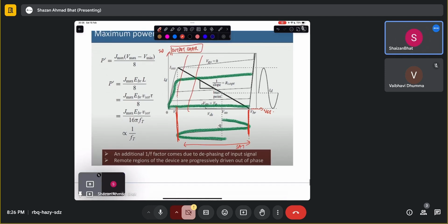This region. You want it all together to be in this particular region, so that it is in the saturation region and it should act like the amplifier you want it to act. And also the current swing should not go beyond this value, and it should not be minimum here. You definitely don't want the current to go below this value, otherwise the current will become zero, and you don't want the current to overshoot this particular value, otherwise it will create breakdown.